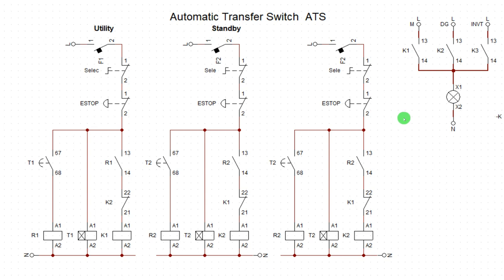So they're going to just take away the inverter supply here and replace it with a gen set. So you don't need to make any alteration on your ATS. ATS will just take over the second gen. So the logic here will take over the second gen. You now have gen 1, gen 2. So leave this logic the way it is. Don't take away the timer.